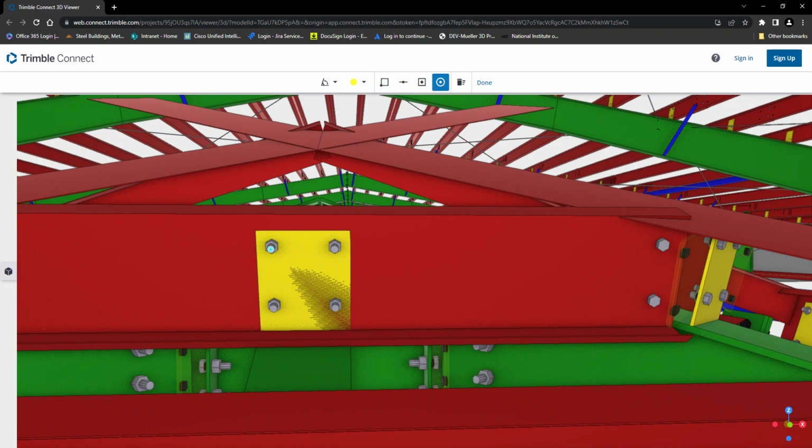The default snap setting is auto, which will snap to the closest point, edge, face, or center that your cursor is near. Also, you are not limited to only selecting one snap preference. When 2 preferences are selected, the application will snap to the closest selected option that your cursor is near. This concludes the measurement and snap options section.